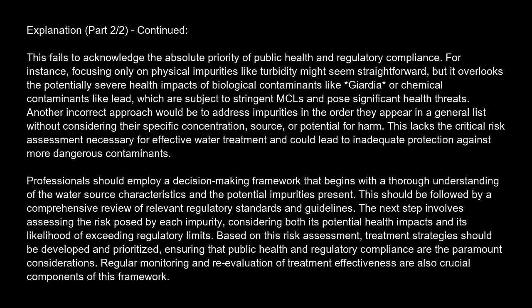For instance, focusing only on physical impurities like turbidity might seem straightforward, but it overlooks the potentially severe health impacts of biological contaminants like Giardia, or chemical contaminants like lead, which are subject to stringent MCLs and pose significant health threats. Another incorrect approach would be to address impurities in the order they appear in a general list without considering their specific concentration, source, or potential for harm. This lacks the critical risk assessment necessary for effective water treatment and could lead to inadequate protection against more dangerous